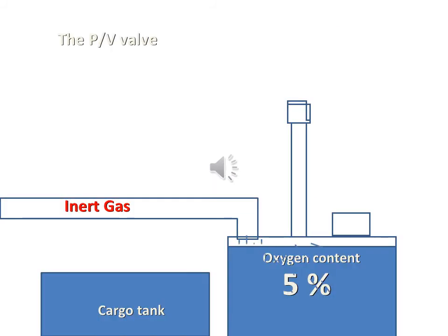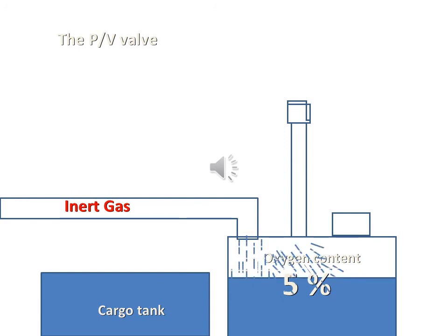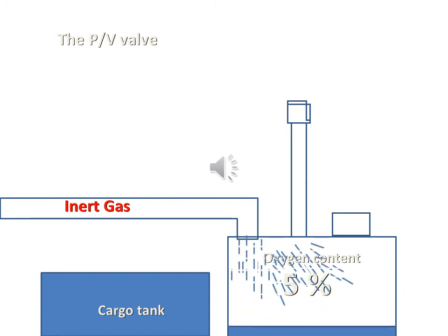Monitor the cargo tank oxygen level, pressure and temperature throughout the cargo oil discharge operations. During discharging, the monitoring of cargo tanks not connected to the inert gas system shall be done more carefully and more frequently. Watch the temperature. Ensure that the oxygen level is maintained below 8%, preferably below 5%.